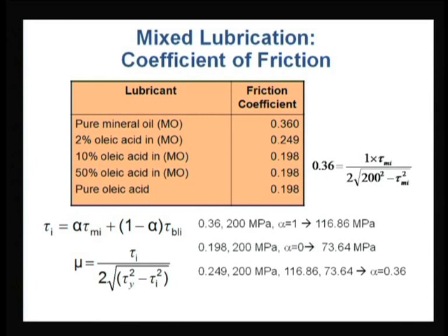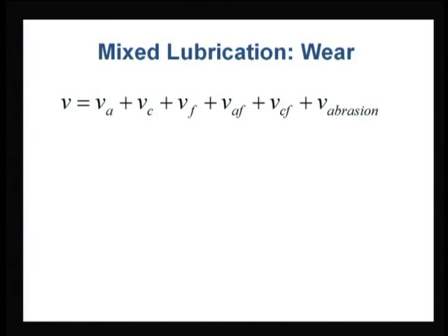Of course, this is a very simplified expression. It does not always hold, but it gives a reasonably good idea about the effect of boundary additives or percentage on surfaces. Now we will come to the wear mechanism, the wear in mixed lubrication. It is interesting. The first and fundamental rule says that wear will never occur on its own. Only one mechanism will not finally lead to failure. It is always a mixture of wear mechanisms which will cause final wear.